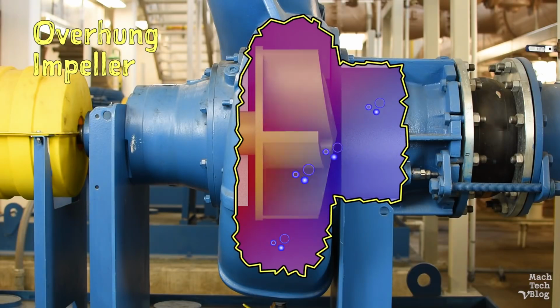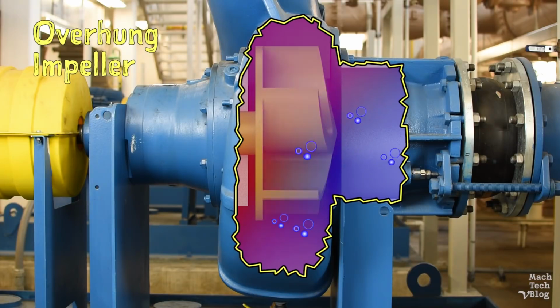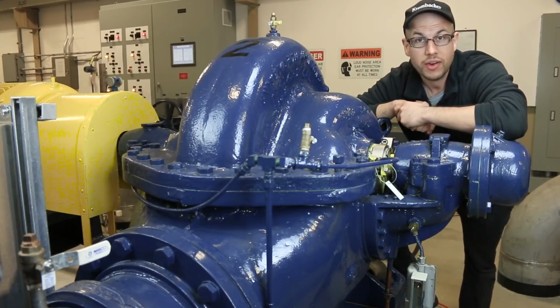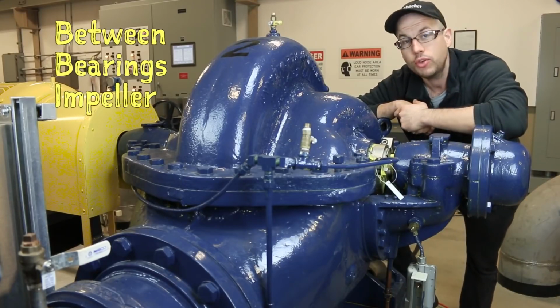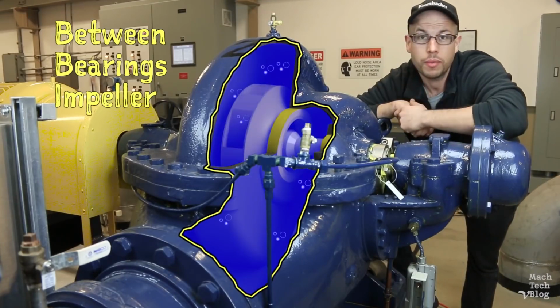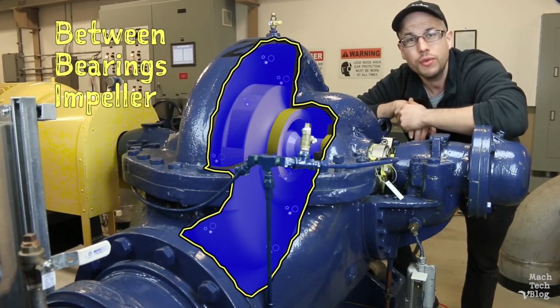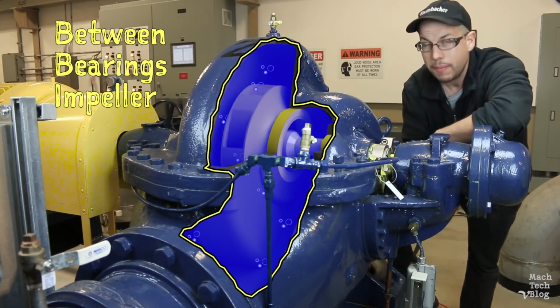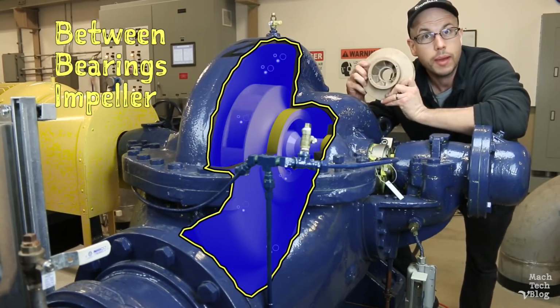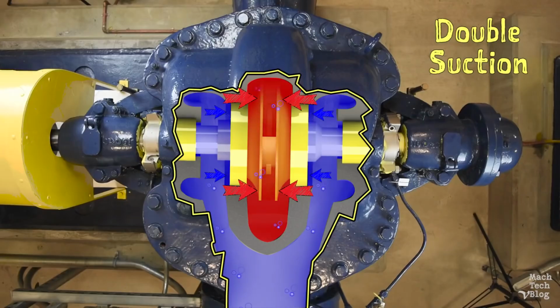But neither of these are true fixes for the problem. A more effective solution is presented if the impeller is supported by bearings on both sides, called a between bearings configuration. Not only does supporting the impeller with bearings on both sides generally improve shaft support, it also means that many of these pumps can employ symmetrical closed impellers with double suction. Since there are identical low and high pressure zones on both sides of the impeller, this effectively eliminates thrust forces